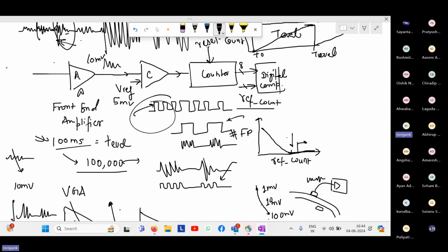If the signal processing person tells you that the sensor is giving us a bigger signal, say a 10 millivolt signal already, then even if you put a nominal gain of just say 5x, that will give you a 50 millivolt signal here, and then you have a comparator over here.